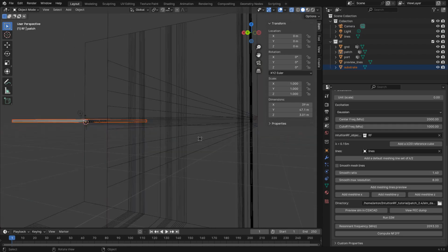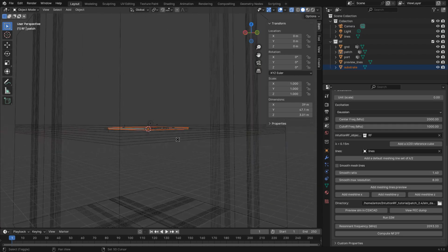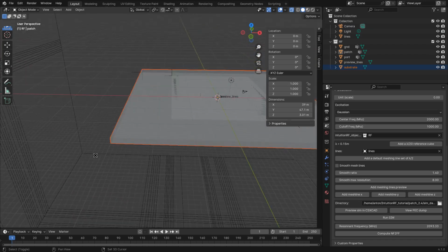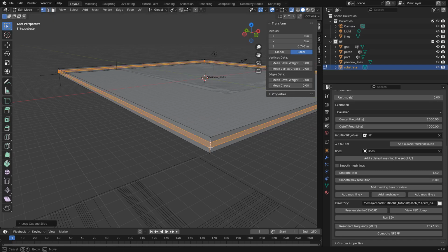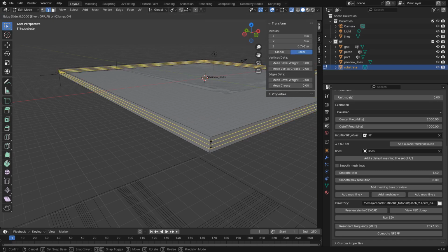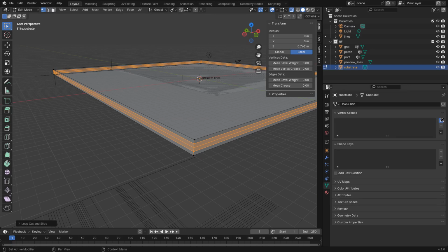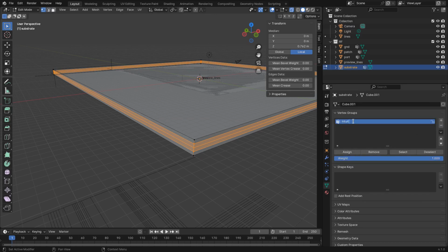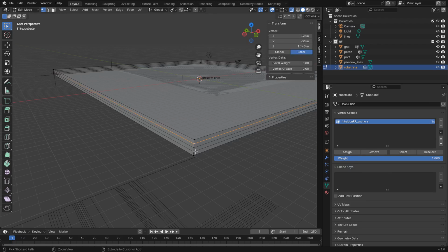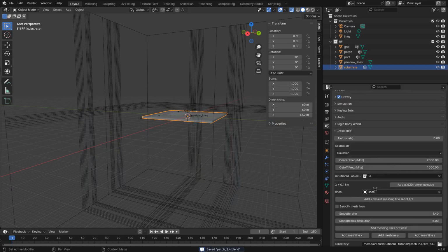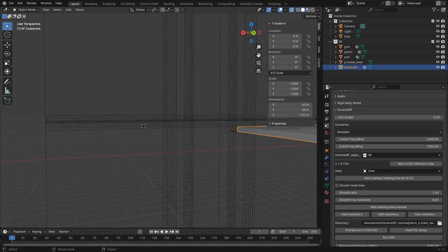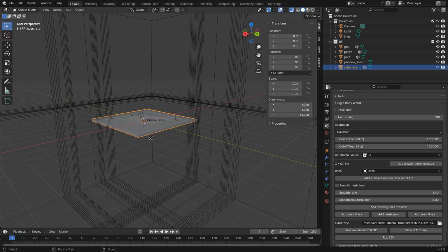And now, as you can see, we don't have a lot of resolution inside the antenna where quite a lot is happening, so we can take the substrate and add some resolution inside the substrate. So let's go 3 cuts, 3 edge loops. Like this. Oh, sorry. Like this. And if we mesh again, like this, we have a much finer resolution inside the antenna. Okay.